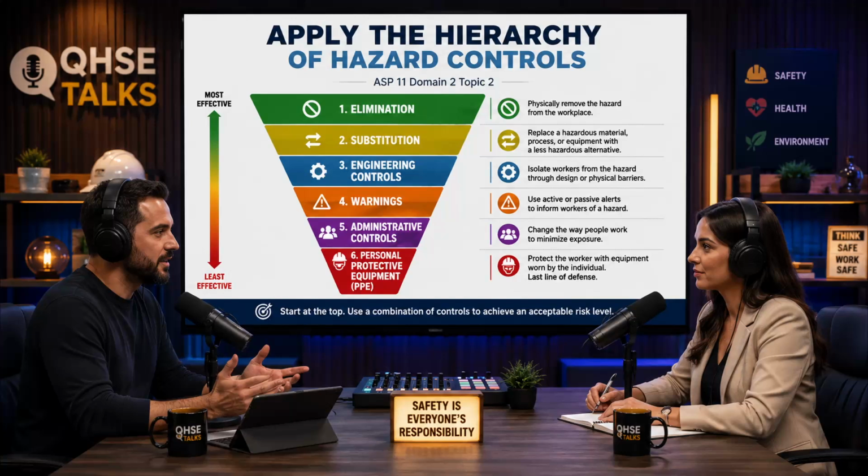But within the strict framework of the hierarchy, that is the wrong answer. Earplugs are personal protective equipment. They are the bottom of the barrel. The actual best protection in the engineering control is to physically enclose the entire forge area with heavily engineered, sound-dampening acoustic material. Exactly. While the operator controls the machine from a console located entirely outside the enclosure.